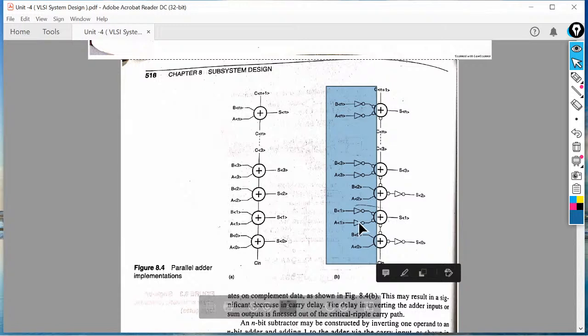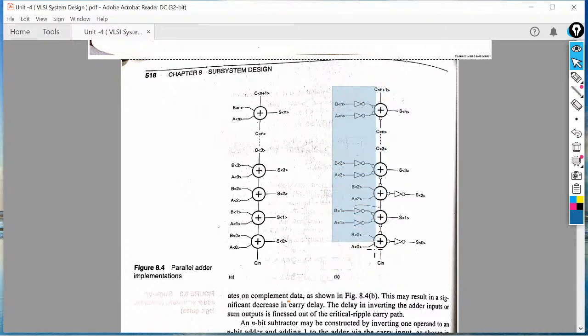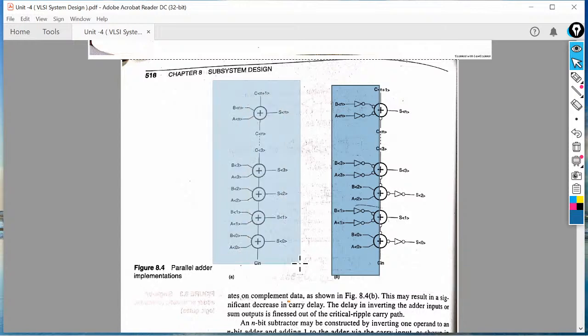Why did we do this? Because in this case the designer's main consideration is speed. The designer wants to design a circuitry for the requirement of higher speed, so at that time you need to add these not gates to speed up the process. If the designer's main requirement is area, you cannot use this type of not gate in the circuitry, because of this logic element along with the routing paths, it takes a larger area as compared to this simple circuitry.